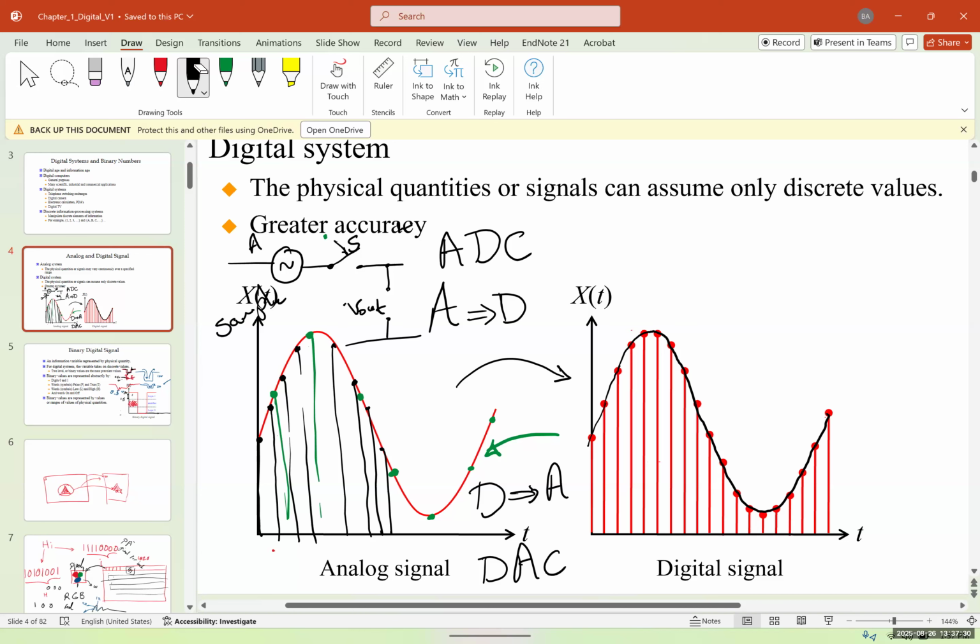You can just use a switch, and you can actually use an op-amp, different types of things; we use different types of parts for that. You can do it with a computer, or with a relay, depending on the voltage and the frequency that you have. The principle is very simple: you have a switch, you just rapidly turn it on and off. When you close the switch, you're going to have a V out, which is a sample. When you open it, you don't have voltage. So you're just going to open and close the switch. Okay. Is it clear, or do you want me to explain more?